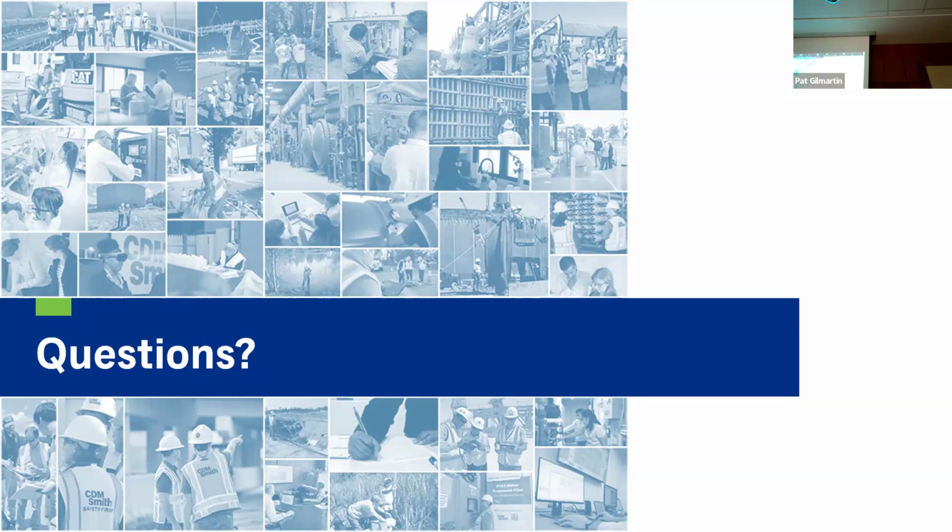And so when you're in really coastal environments with sands, the contractor is going to have a little bit denser of a mud in order to keep the mud from just going into the formation. If you start getting into cobbles, boulders, things like that, the void space may be too large and you'll just get all the drilling fluid flushing out of the hole. So it's mostly boulders, cobbles, and more like man-made structures that are the issues.